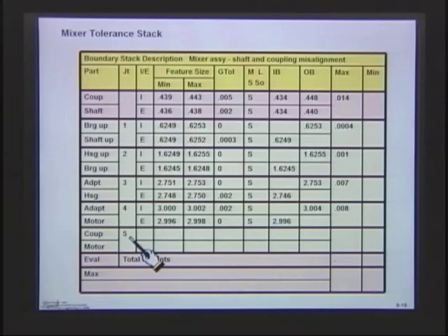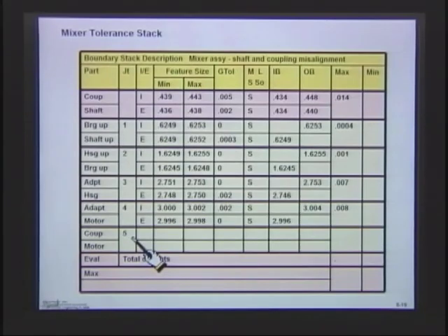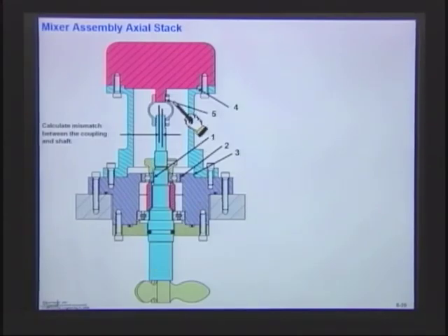We're going on to joint number 5. Let's see where it is. Okay, that's the coupling. That's where the motor attaches to the coupling. And probably what's going to happen is when you tighten up the set screw in here, it's going to push it to one side, so we'll certainly have that misalignment there. So let's take a look at what we'll have.